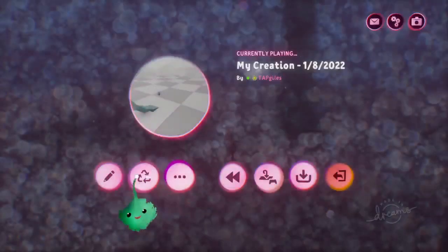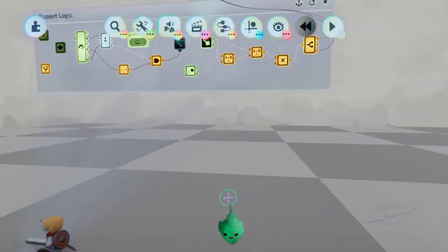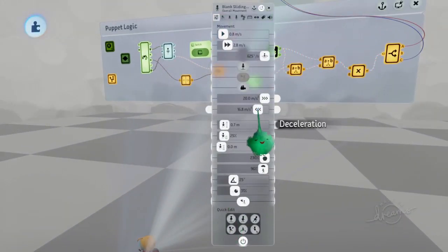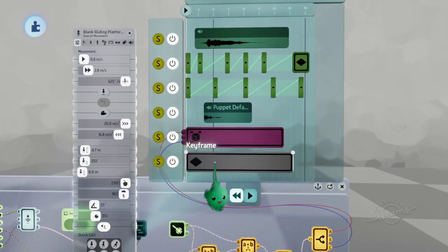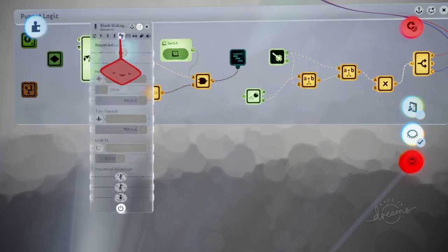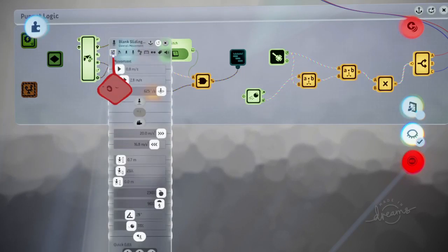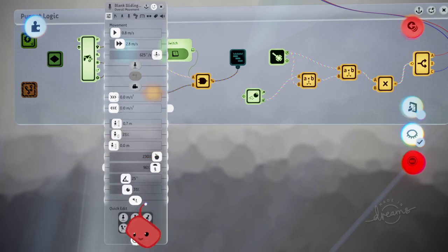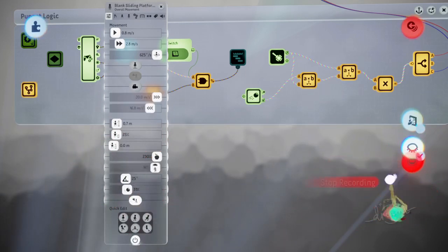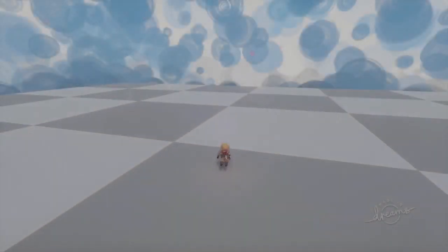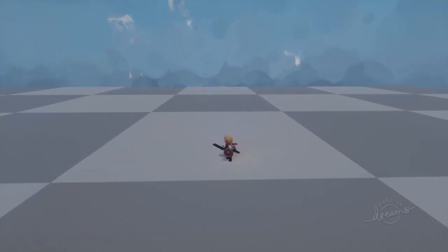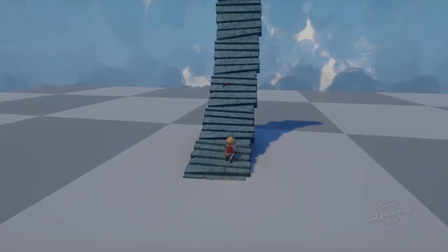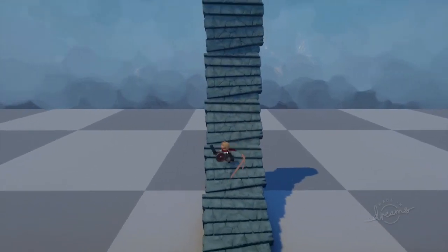So cool. What we can also do to help it is turn off the deceleration and acceleration stuff, because we want to just control the movement with this. So this is already turning off the procedural animation, and we can turn off the acceleration, deceleration, and air control probably. Nice controlled roll there, and going up the hill, going down the hill.